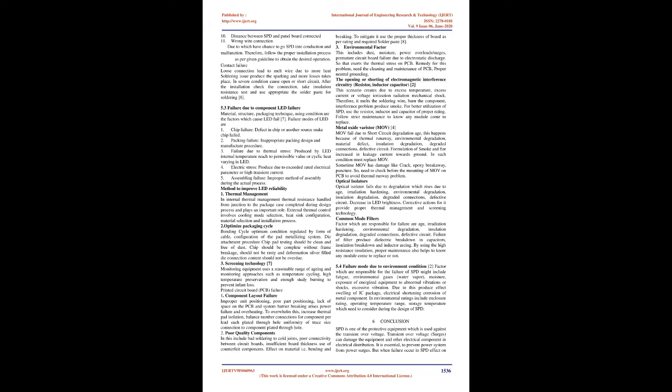11. Wrong wire connection, due to which there is a chance for the SPD to go into conduction and malfunction. Therefore, follow the proper installation process as per the given guideline to obtain the desired operation.